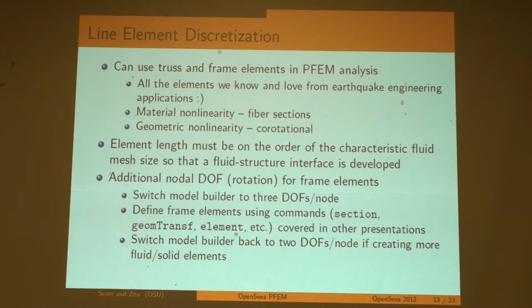Okay. And we can also do line element discretization to get solid elements, or structural elements, I should say, that are truss or frame. Okay, so all the elements we know and love from earthquake engineering applications, like with fiber sections and co-rotational transformations to get material and geometric nonlinearity, they can be used with this PFEM analysis.